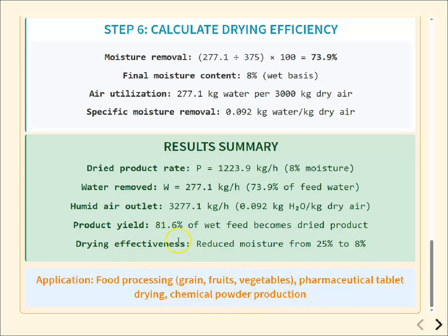So from this problem, the key takeaway is: always remember that dry solid remains constant in drying operation. This principle simplifies all your calculation.